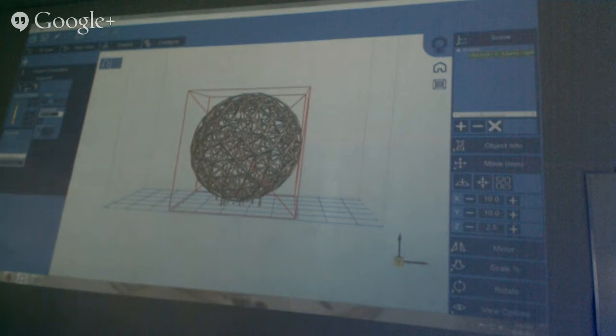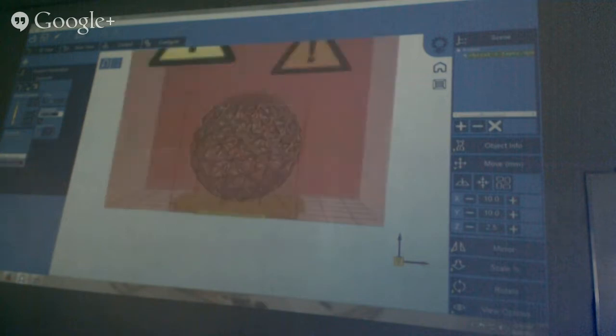With this, the center icon here is the attachment layer, base layer generation, that gives you one layer thickness, and it is 1 millimeter thick, and that is too thick for SLA type of printing. With 1 millimeter thick, your model will probably drop because of shrinkage.